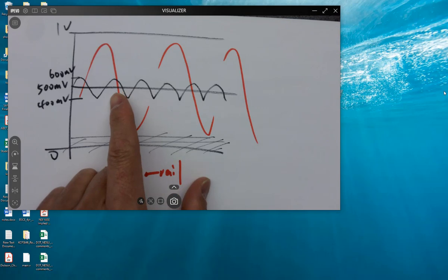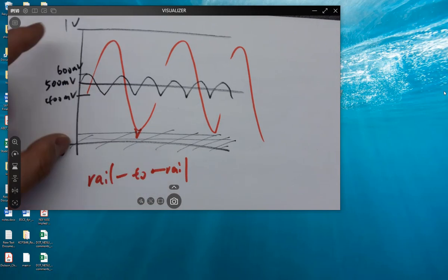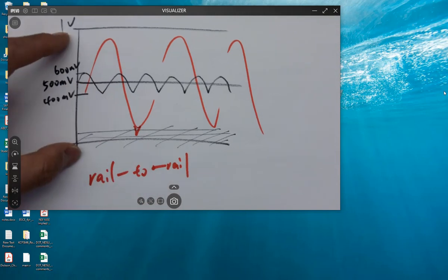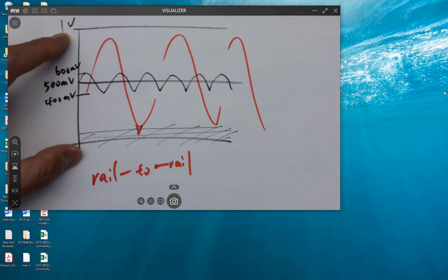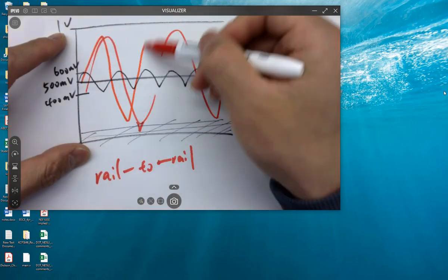You will never use analog signal directly from the sensor because it's not being processed. You can see this is already pre-processed. That is why it's adding a perfect DC offset. It's lifting the AC swing to the middle of the range, so you have the best swing room to the top and bottom.